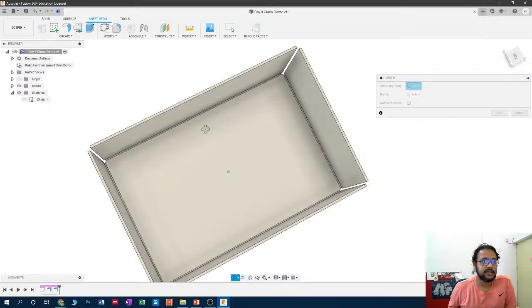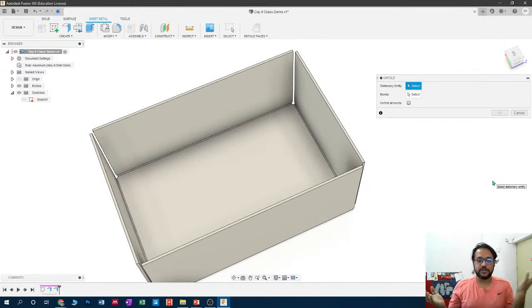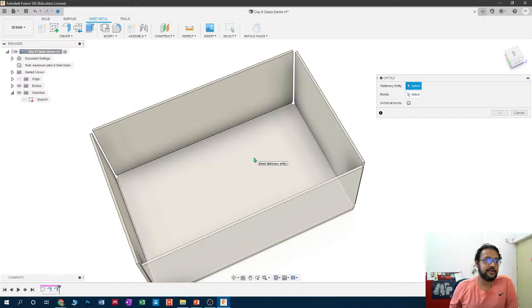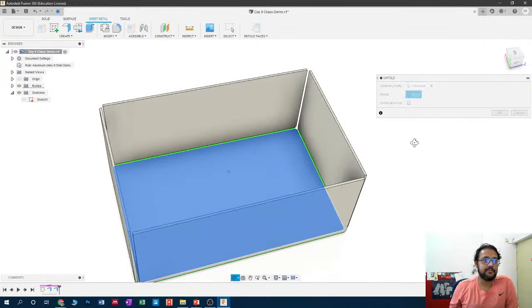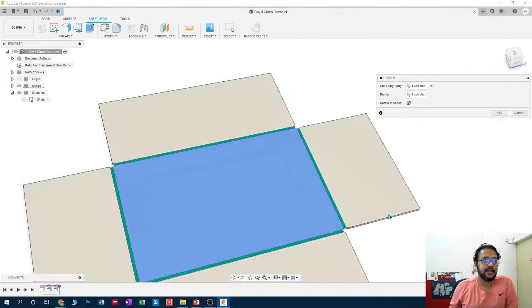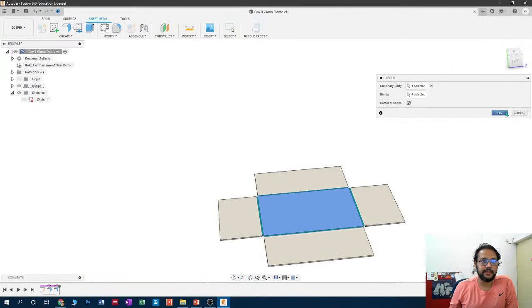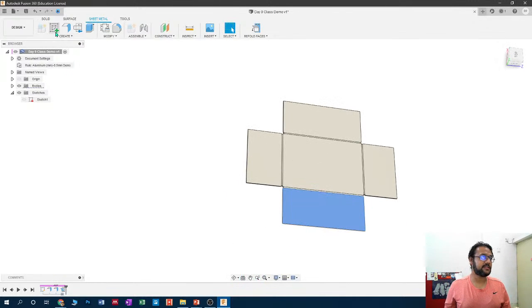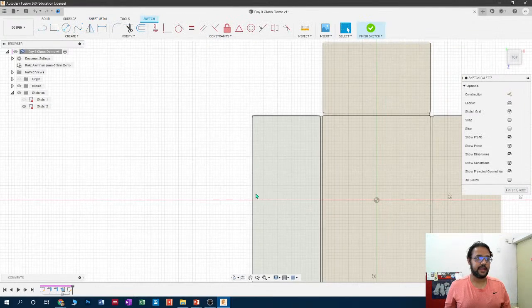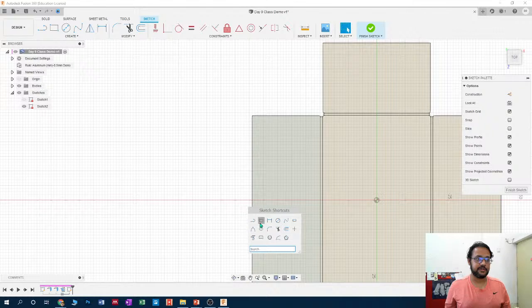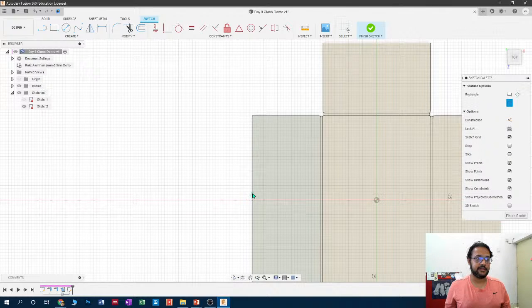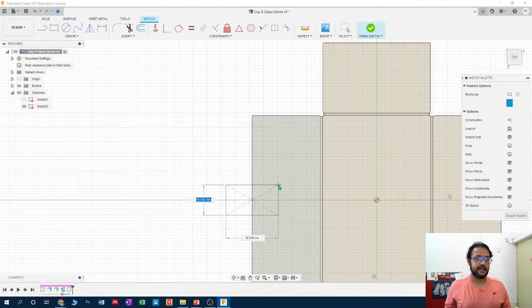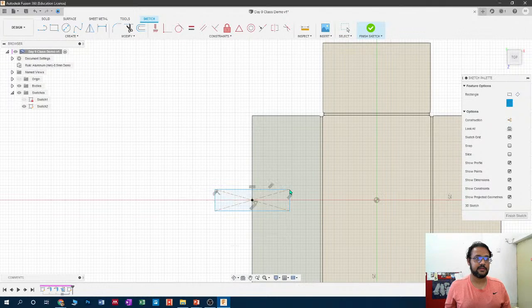When I select this, I'm trying to unfold the whole thing and see how it looks unfolded. So I'll select the part which is stationary. I want to select this face which is stationary, and the bends, unfold all bends, I will say, and this is what it looks like unbended. Now on this surface I will create a sketch and I will cut out some part of it. Let's say I want to cut out this much.